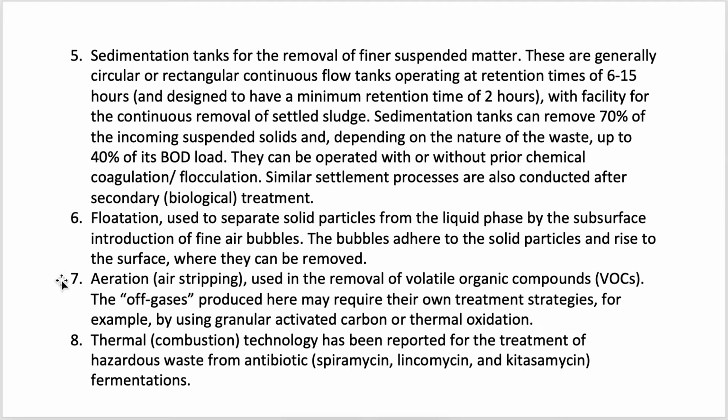Then aeration. Aeration is used in the removal of volatile organic compounds. However, aeration may produce off gases. If off gases are produced, they themselves require different treatment strategies. One strategy can be the use of granular activated carbon or thermal oxidation to remove the off gases produced by aeration.